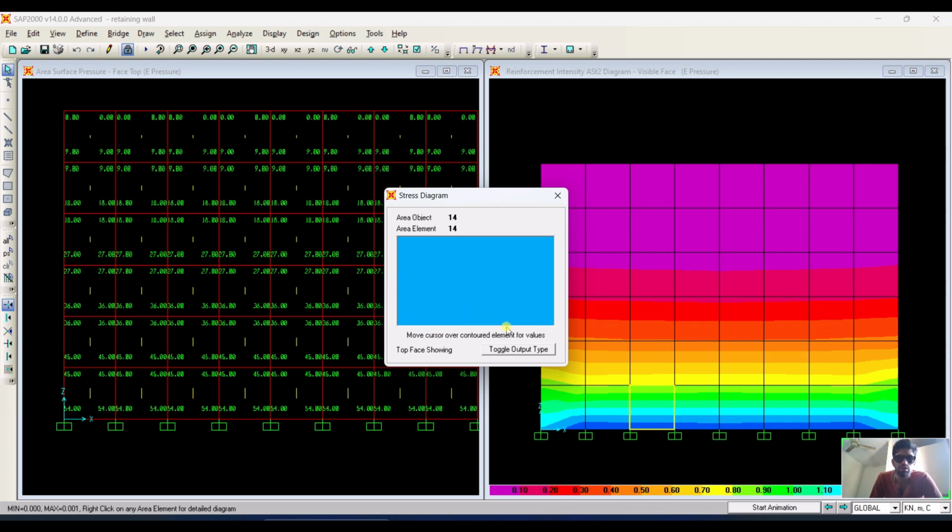Here, if I take my point here, the unit is square meter per meter. This is the area of steel bar per meter. Per meter means this length or this length, depending on your direction of reinforcement. These are the two, AST1 and AST2, as I already told you.